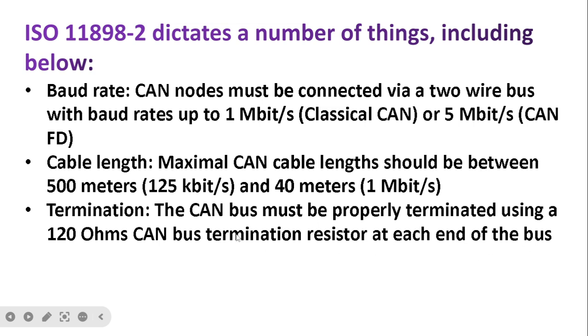In this communication there is a frame, meaning the whole process starts from a single frame which starts the cycle and ends the cycle. So at the start and at the end there is a 120 ohm resistance. The diagram will be shown in the next slides. It is used to reduce extra signals, to preserve the signal, and to avoid damage to the signals.